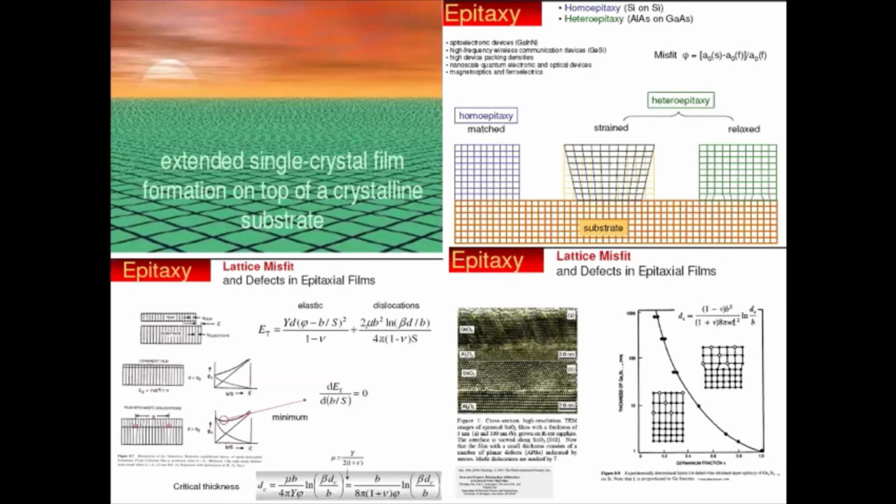Say, for example, for an LED, we need to have a PN junction. Then, when you give the forward bias through proper metal contacts, you have the electron hole pairs created at the interface, and finally they produce photons. And depending upon the nature of the biasing and the external voltage, you have what is called spontaneous as well as stimulated emission. So either LED or the laser diode.